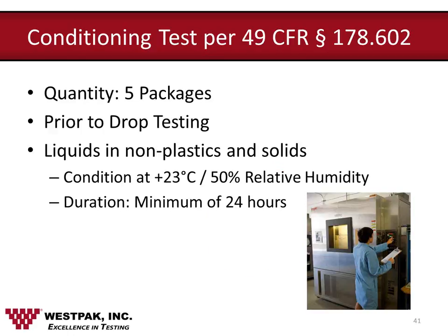The first thing that you would do for your package systems is conditioning. With conditioning, you need 5 different packages. The reason why you do conditioning is because you want to acclimate the packages to normal ambient temperatures and humidities prior to drop testing. Sometimes your box will come from a place that's really humid, or on the flip side, from a place that's really dry. So we want to make sure that when you're testing these boxes, whether they come from Florida or California, you're all testing to the same conditions and all boxes are created equal, to say the least. So you condition them at 23 degrees C and 50 percent relative humidity for a minimum of 24 hours. However,